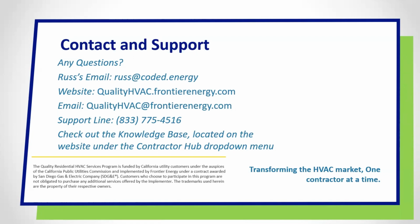Okay. And there's a lot of opportunity out there to downsize equipment. This problem has been going on for a long, long time. I would say the vast majority of homes in California have oversized equipment and undersized ducts. Especially if you're going from a gas furnace to a heat pump, evaluate that, figure out exactly what the house needs, figure out if there's opportunity to improve the house, and then take that opportunity to put in a smaller piece of equipment. And who knows, maybe your ducts might end up being properly sized for the smaller piece of equipment than they were for the original one. So there's opportunity out there.